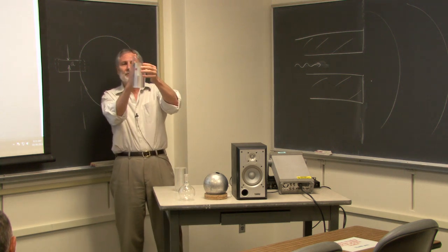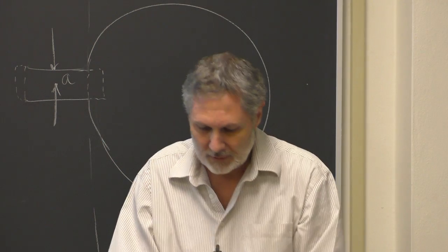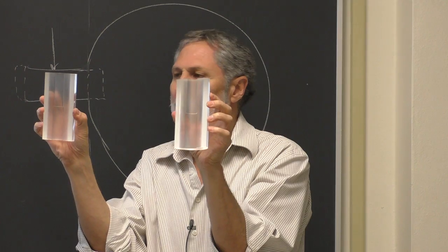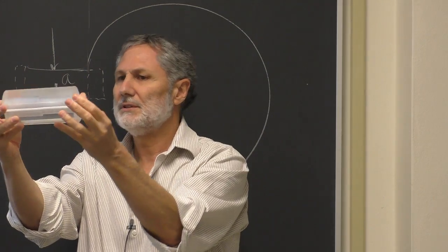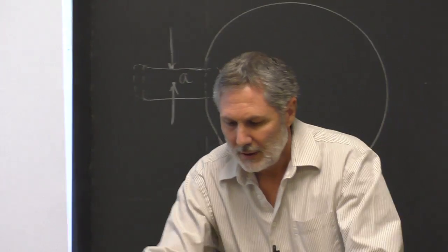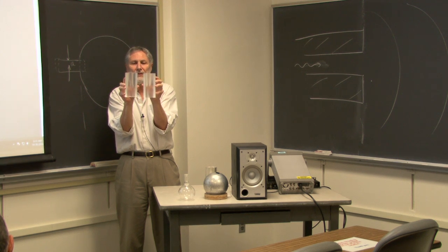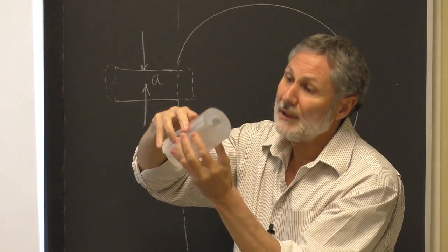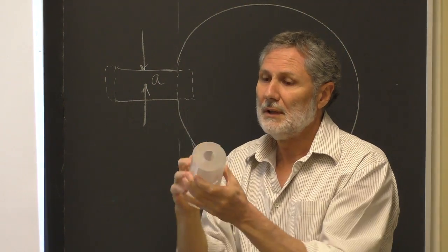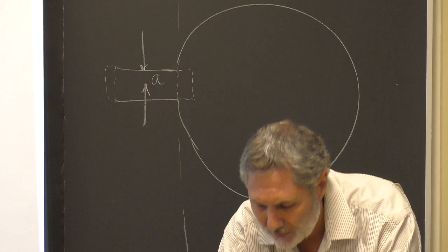Well, you can imagine here, if you imagine cutting this into two halves. The ratio of the diameters is different here, but you can see there's a step there, right? Can you see the step there? Does it show up? No. So you can see the step there. Why would you want to do this? Well, the reason is now you can get a third frequency. You can get this one, you can get that one, and then you can get one where it just makes a jog. So if you go through the calculation, you can come up with a musical scale, the first three notes of a major scale.